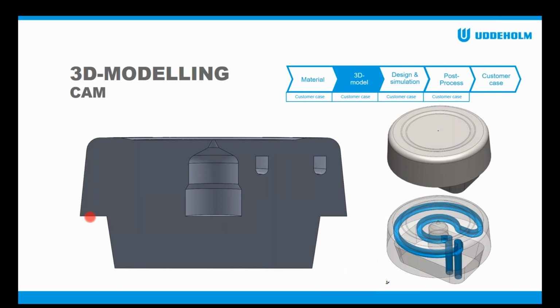So for this surface, for example, there's nothing underneath here. Imagine that the part is built by layer, from the bottom up. And when you come to this layer, nothing underneath will support this part. So here the printer would need to add something that we call support material, or actually, it's the general term.